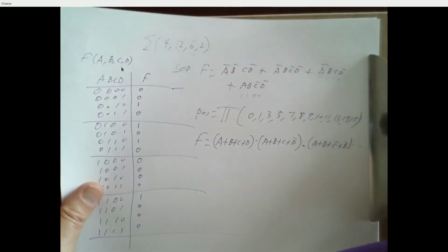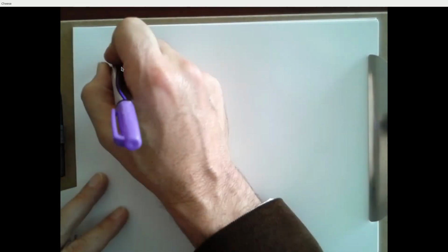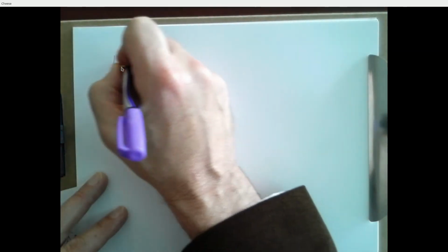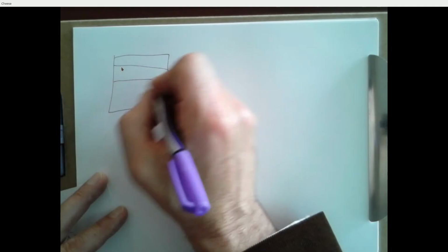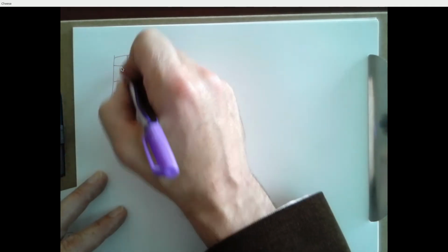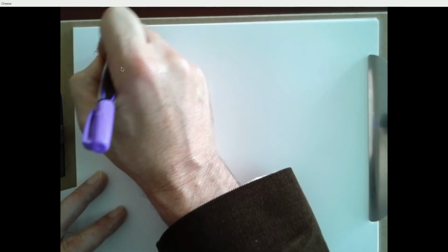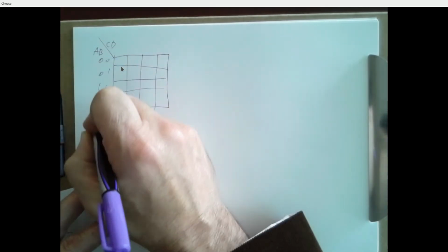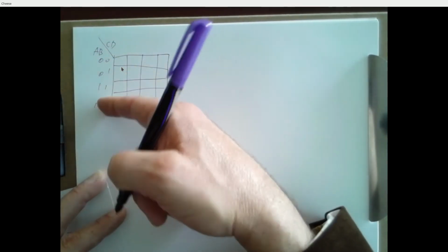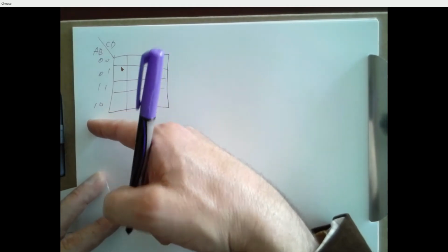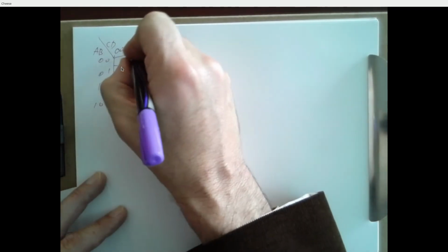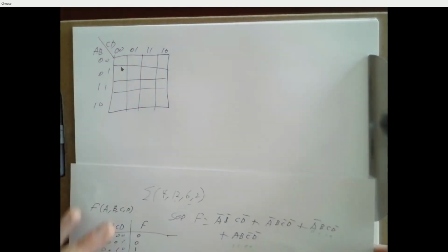All right, and then the K-maps. For sum of products, most people were spot on. Make sure it's 0, 0, 0, 1, 1, 1, 1, 0. There are a few cases where they went in traditional order instead of that correct order.